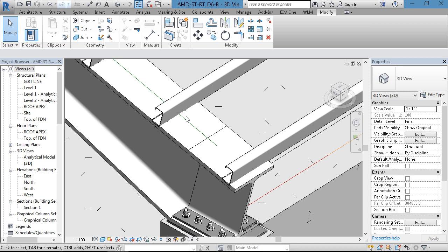Can you click that pattern? Then select that, the line. Okay. Click that. And then you add parameter. Click that one. And then say number of purlins. Number of purlins.